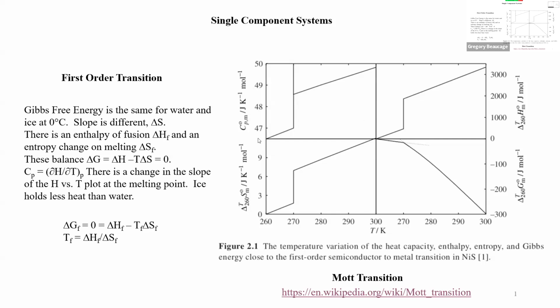One reason not to do that is this heat. It isn't so clean cut as this. Like this is measured in a DSC. You go through this transition, and everything is squared out. But in a real transition, these things are rounded out, so they aren't necessarily so clear cut that there's a delta function here. And then the heat capacity is a broad hump here. It isn't just a spike. So I think the reason he's going to a Mott transition is just to show you what it should look like in a model situation where you don't have kinetics involved in it.